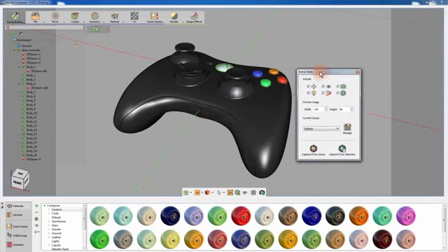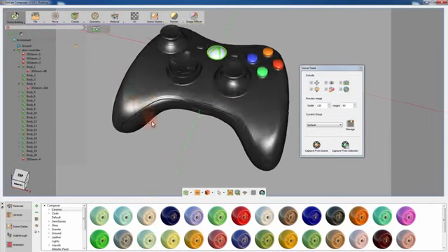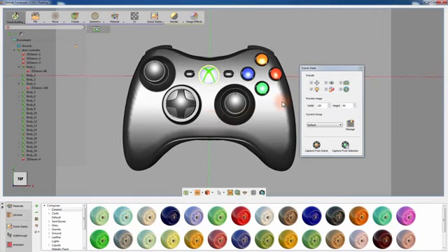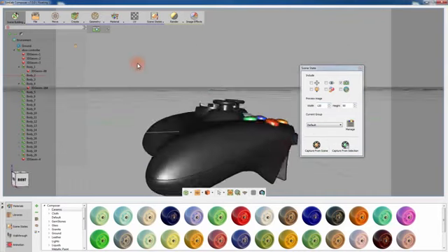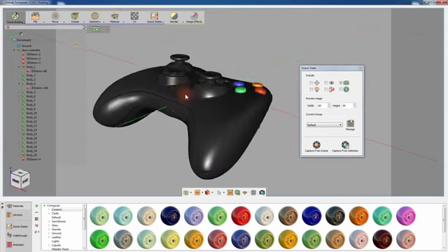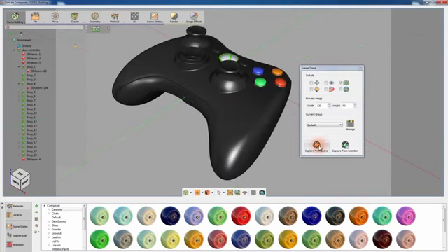a few. To create a scene state for the camera view, set your viewing camera in the desired angle and disable all the attributes from the Scene States Manager except for the camera attributes, and then click Capture. You can save multiple scene states for the camera by simply changing the angle and clicking Capture.